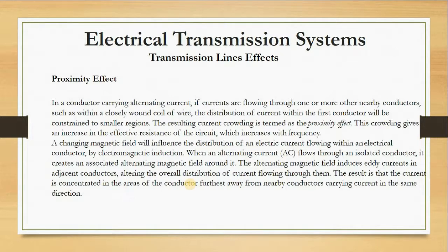As it reduces, you expect it to collapse. Now, when the current is changing or alternating, you expect the magnetic field to also be building and collapsing, that is, changing. And according to Faraday, when any circuit links a changing magnetic flux, an EMF is induced in that circuit. When an EMF, which is electromotive force, is induced, it means that it can cause current to also flow in that circuit. So that means that if you bring a conductor